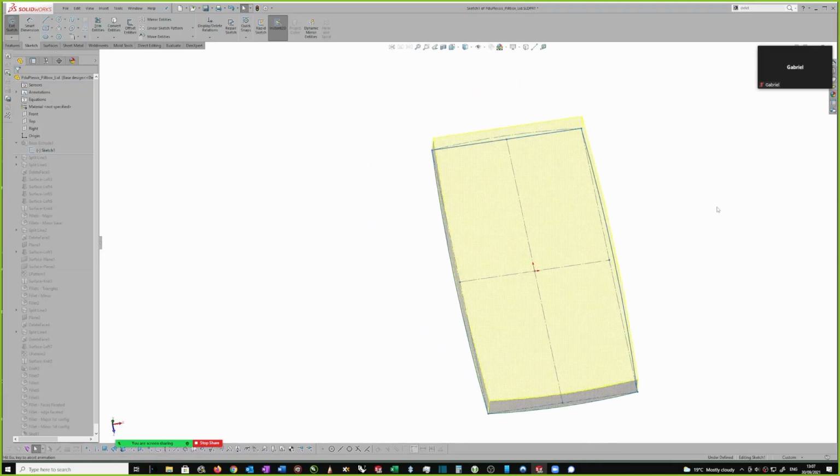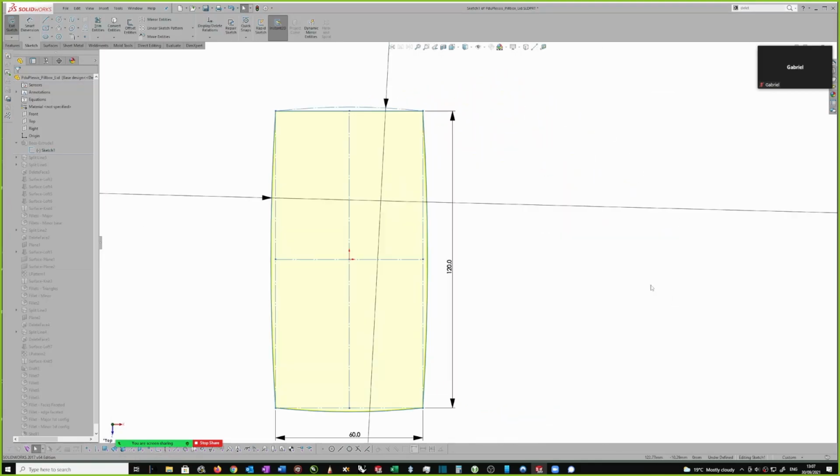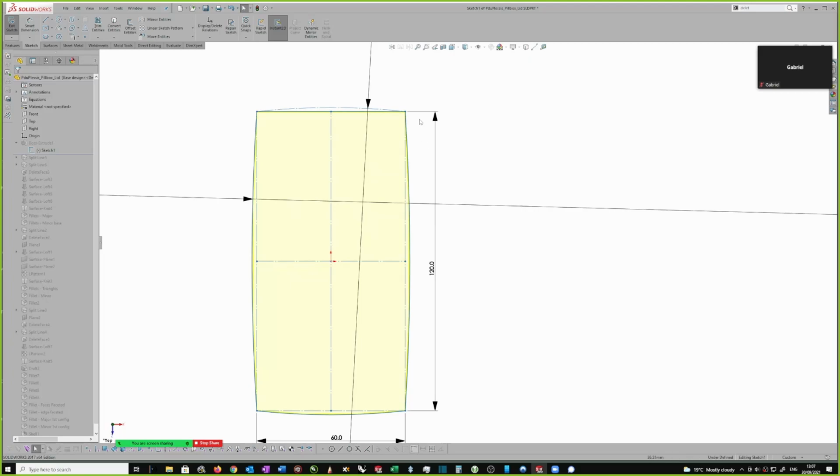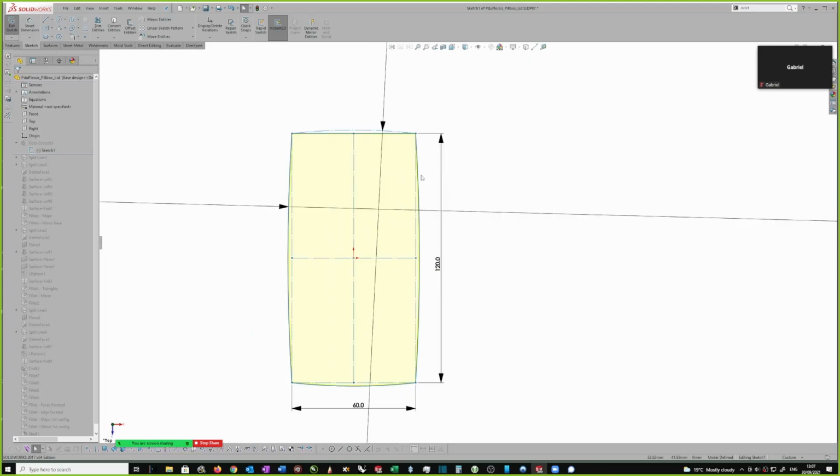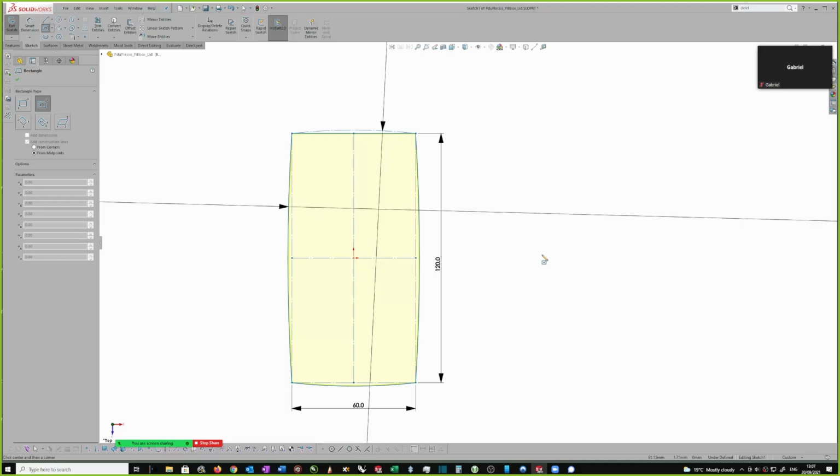This is just reminding you of what's useful and what's good. Whenever you're doing a sketch, it really is a good idea, if it's symmetrical, to put it symmetrically around the origin point. So that's what I've done. I started off with a square, so I went like this.